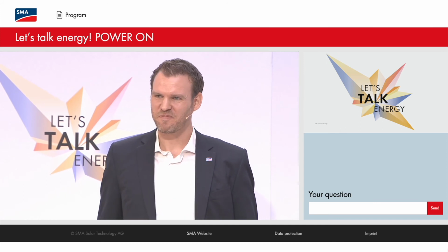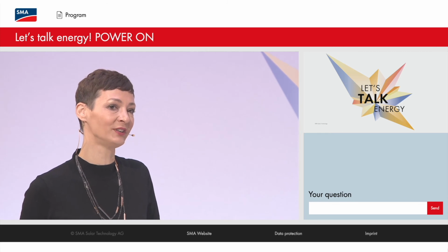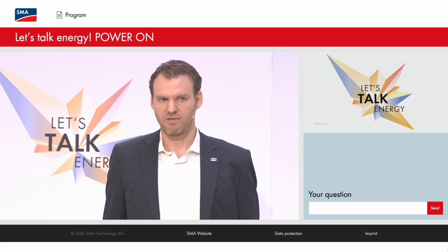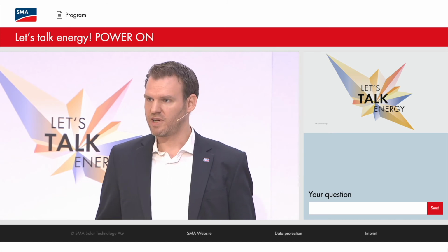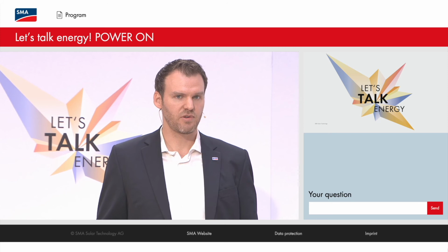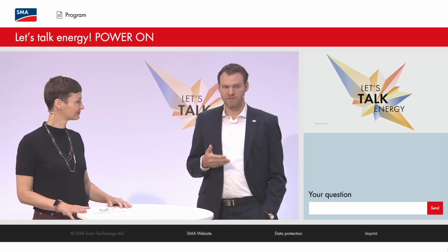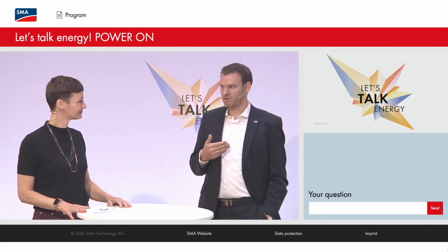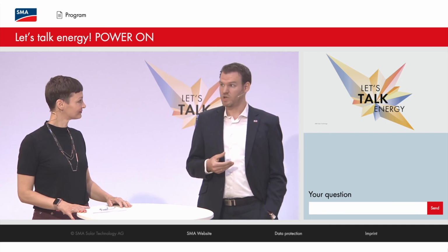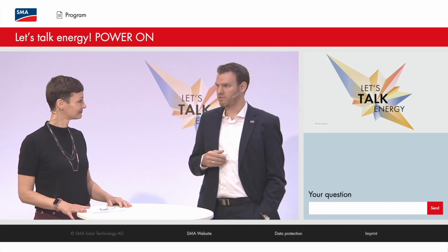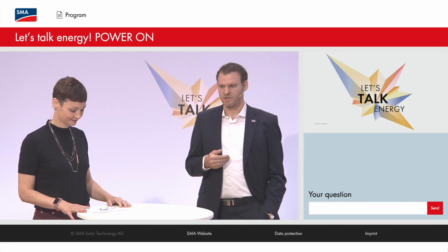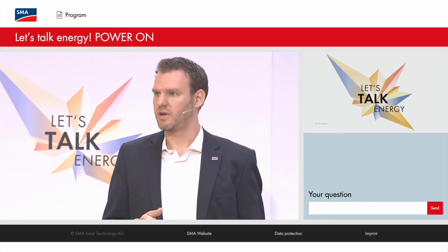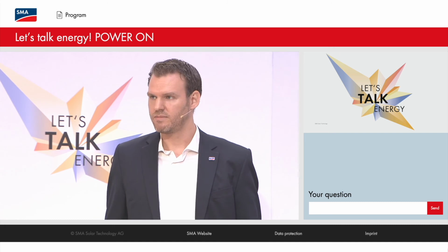Absolutely. Okay, so we would like to know next, what's better for storage, string or central inverter? We had it on the slide. It really depends on the application. There's residential and commercial applications for storage. Obviously, there you have string inverters. String inverters provide some nice scalability. But when it comes to response times and grid compliance, especially in storage, this is really key, with a next session about storage in detail. The central inverters have quite an advantage with regards to being very responsive and also being grid compliant.